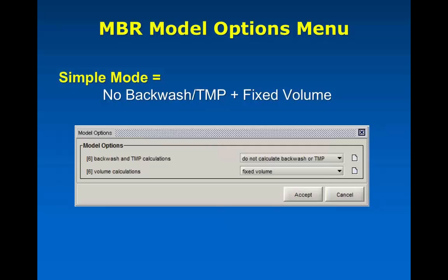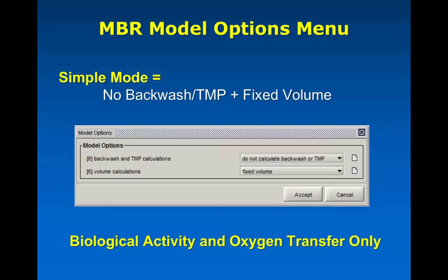We will have the appropriate level of solids kept in the system as part of the model itself. You specify the capture rate, which would be 99.9% or something like that. But we don't actually figure out how much of that is sitting on the cake and how much of it is in the liquid. We basically assume that everything is in the liquid. It's all been successfully captured and returned to the bulk liquid.